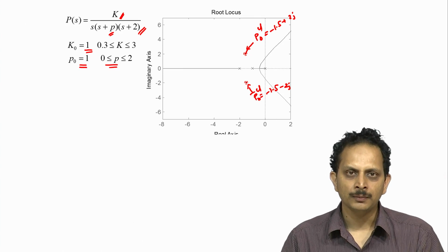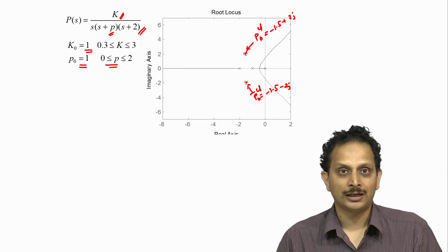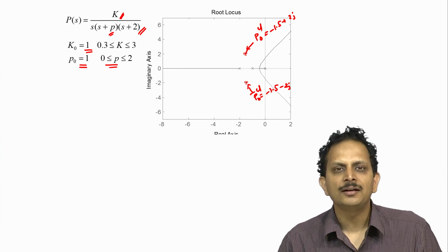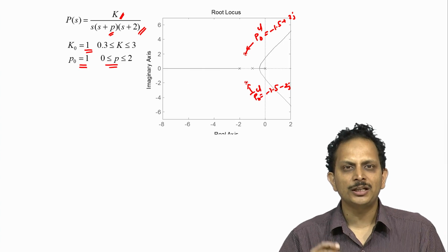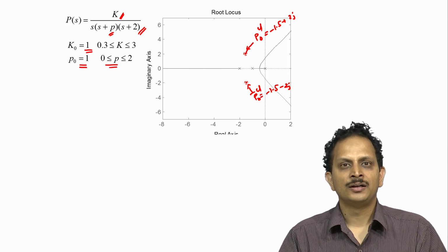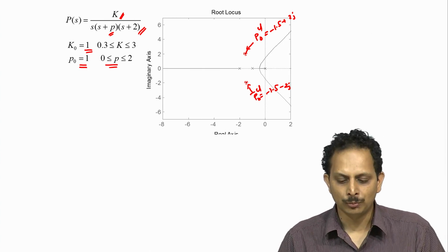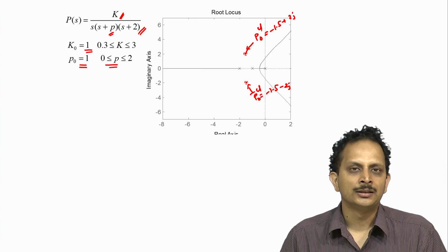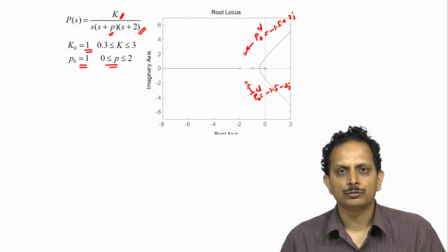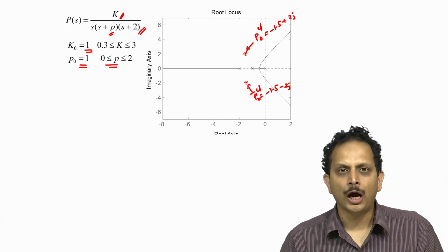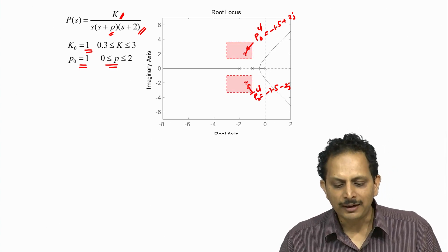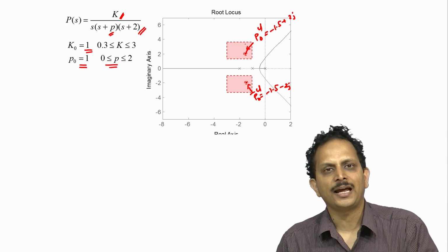and zeros. What we shall do in this clip, however, is to take a look at a problem that cannot be handled using root locus, but is essentially of similar flavor as what we did earlier. In particular, instead of restricting the variation of the closed loop pole to a very small region near the desired dominant pole location, namely at minus 1.5 plus minus 2j, we shall allow for variation of the dominant pole PCL anywhere within these two big rectangular regions.